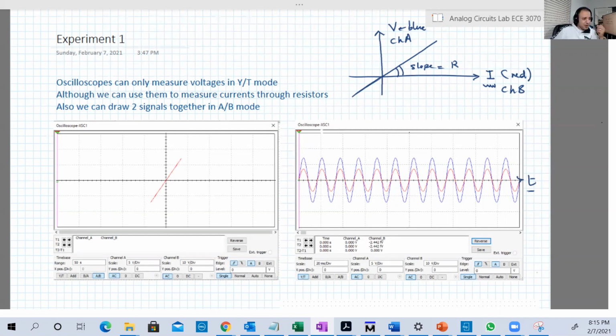We said that this is sometimes tedious if you have, for example, a complex device that has a nonlinear relation. You need many points in your graph, and doing that will be error prone. You will have mistakes. Better to use parameter sweep. Parameter sweep is a super feature in Multisim that makes such kind of experiment very easy.